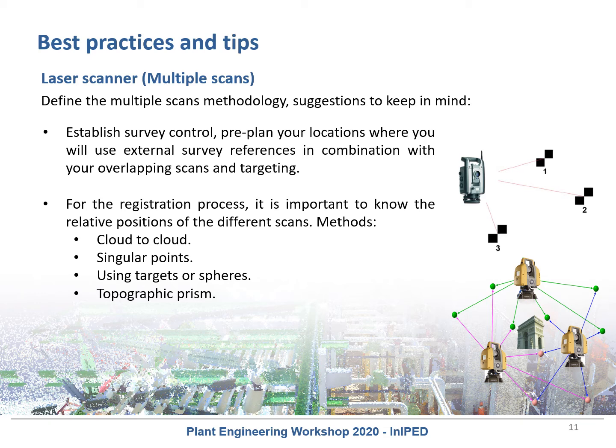Surely, you will have to use external survey reference in combination with your overlapping scans and targeting. At the end of the scan process, you will have a singular point cloud and the relative position of each scan. Now, it's time to join all the singular point clouds obtained into a unified point cloud.